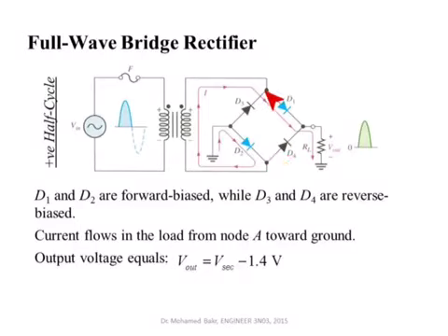The negative terminal of this one is connected to the peak voltage, but the positive terminal will be connected to a much lower voltage. What is the voltage here? It is the peak minus 0.7 minus the drop across the resistor. So this takes us to this point. This one is the peak, while this one is the peak minus 0.7 minus the voltage across the resistor. So this one is reverse biased. Okay, this one, D3, is not on.